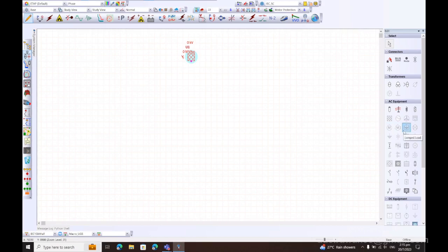I won't be able to connect another utility models to this. So it enables elements that are suitable to be connected based on your reference elements, in this case, our utility. So I will do a very quick demonstration right now to show you how ETAP Auto Build works.